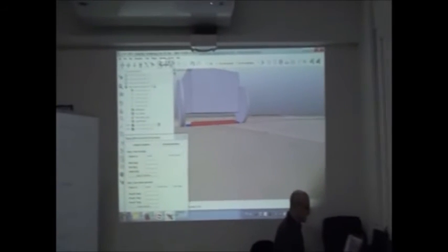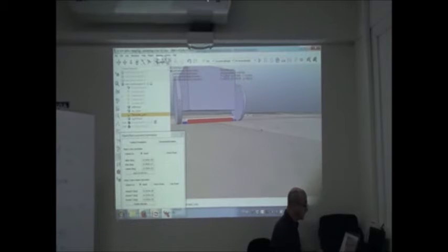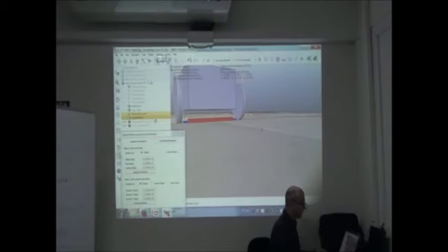Look, you select the joint. You press Ctrl to make multiple selections. You select the first wheel, the right wheel, for instance. Okay. So you see that the bounding box here is yellow. So it means that this was the first thing that you select. And if I select more stuff, you see only the last thing I'm selecting will be white. Okay. I can deselect by re-clicking. Okay. So selecting the joint, pressing Ctrl, selecting the wheel, and now,